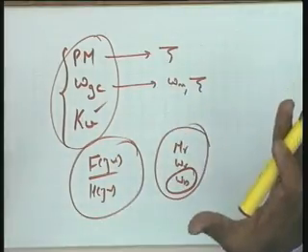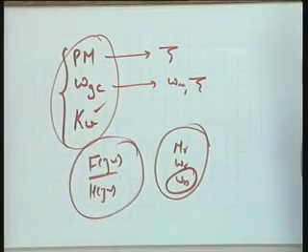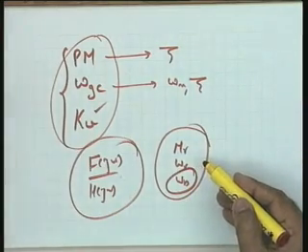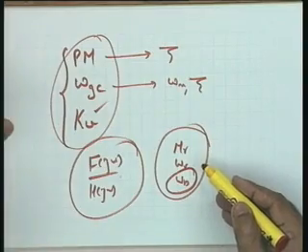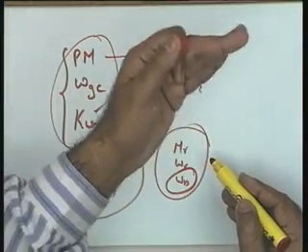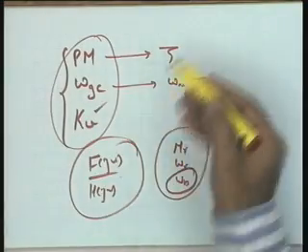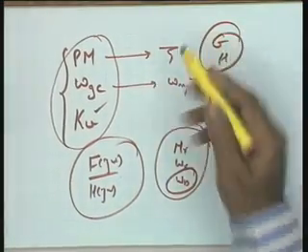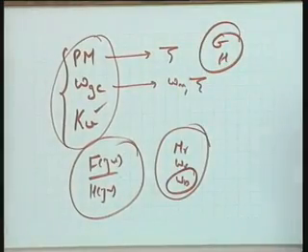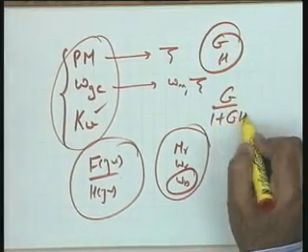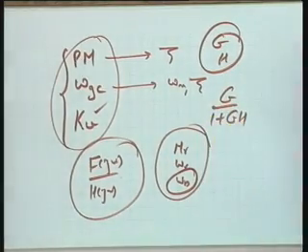Once I have made a preliminary design, I can go to the CAD software, and omega b or any other value can immediately be seen, because for any value of G and H the software gives you the values of Mr, omega r and omega b by solving the equation G over 1 plus GH directly, or you can write your own program.